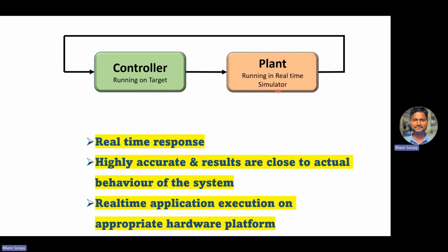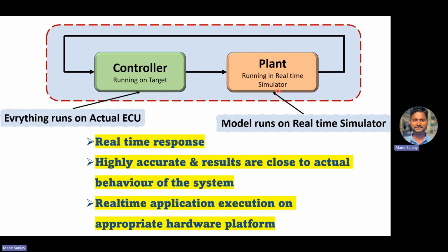But I hope it is very much clear that when it comes to this ECU and this real-time simulator, we have to prepare a simple model for your input and output signal. If you are modeling coolant temperature and it is analog in behavior, you have to simulate that using any software, as I mentioned, MATLAB Simulink or NI LabVIEW or NI VeriStand or AMESim. That way you can simulate it and run that model on a real-time simulator.